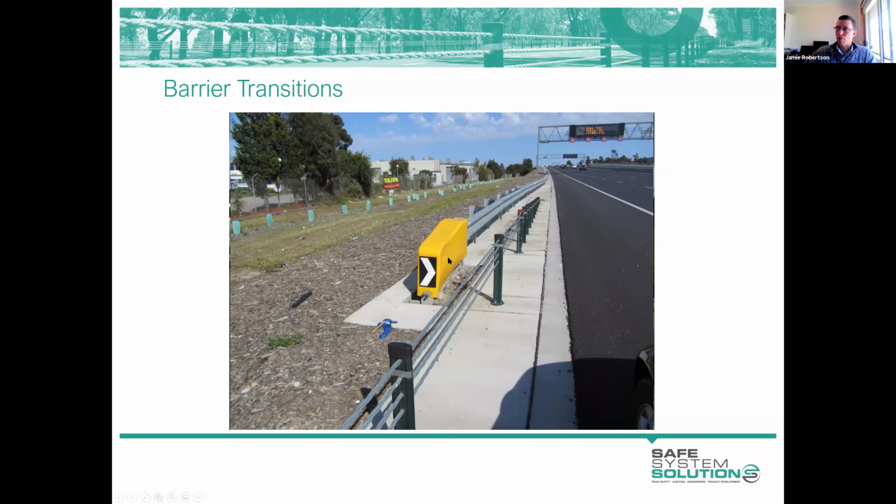You can see that we have got a grate on the guard fence, and I think that was done in recognition of the fact that it was probably closer to the wire rope than it perhaps should have been. And it's hard to appreciate from the photo, but the embankment there really is quite steep. So to have achieved a greater offset would have been a challenge. The good thing about this one is the points of need are overlapped, however.